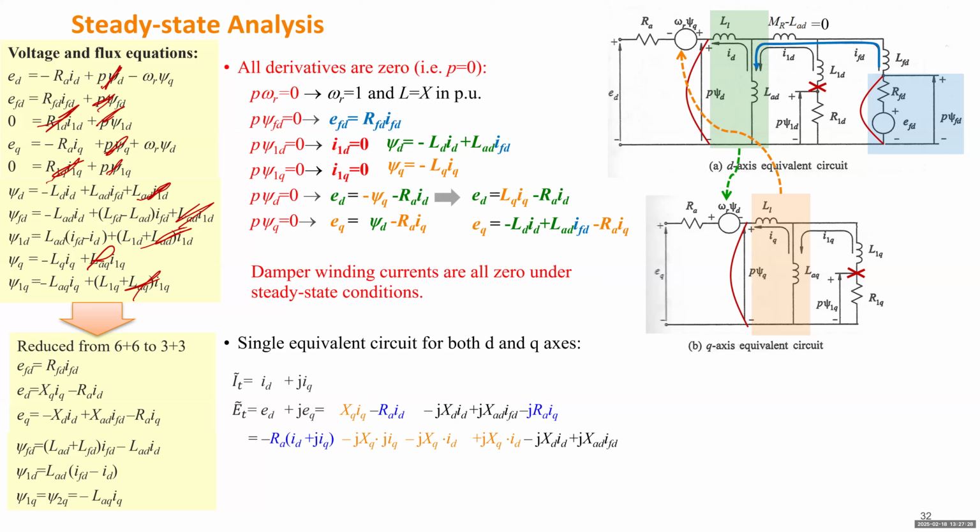Okay. Then for the psi_sq term, it is multiplied by i_q. We need to create one item which is like psi_sq multiplied by i_d, but there's no such item at all, right? There could be psi_sd multiplied by i_d, but that is not psi_sq multiplied by i_d. So we can create one item which is psi_sq multiplied by i_d. And for this item, if you compare to the blue items on the resistance, we know the i_q component comes with an imaginary unit j.